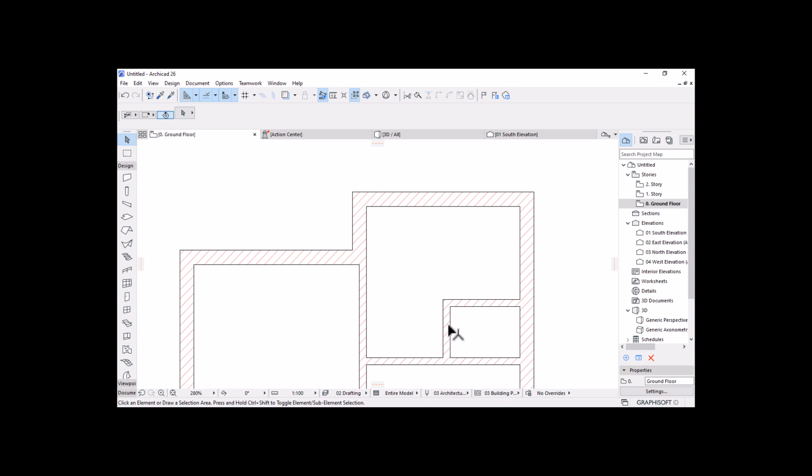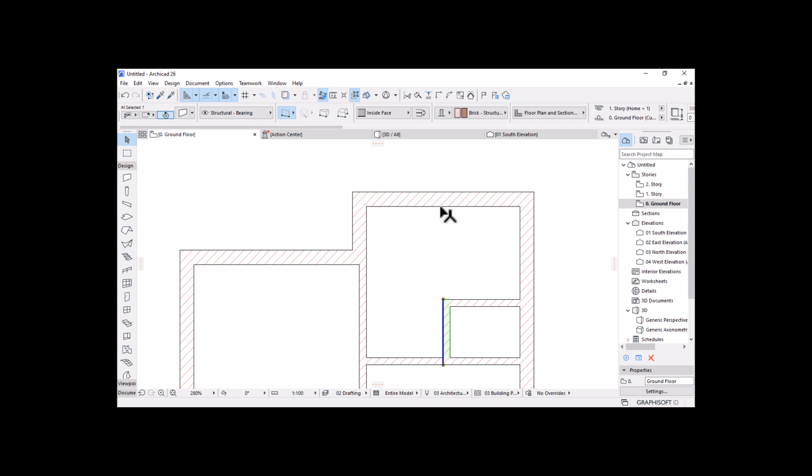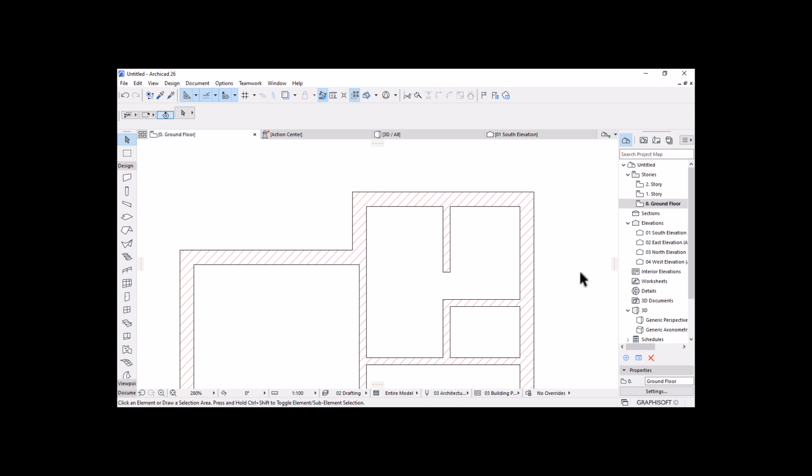So now I'm going to select this wall, and then I want to duplicate this wall to this end, and duplication should be in line with this wall. So I could pick this wall, and then I could drag it, and then going all the way to there. But during the process, I can now add a copy, because right now it's not a copy, it's the original element here. So I can add a copy of the selection by clicking Control in your keyboard. If you click Control, you see now we've added a copy. Our cursor indicates a plus, so now that means we're carrying a copy. I can now come here and then place it or dock it to this wall, right? And then click outside to complete that, right?